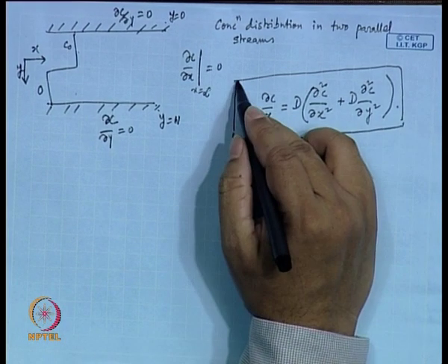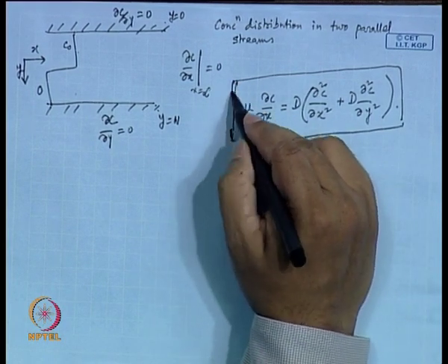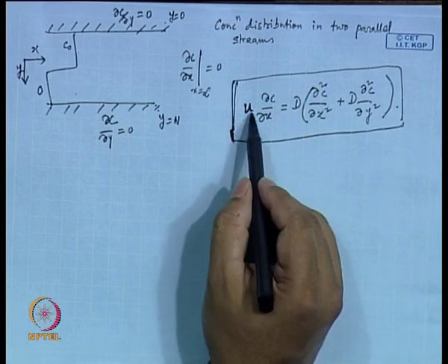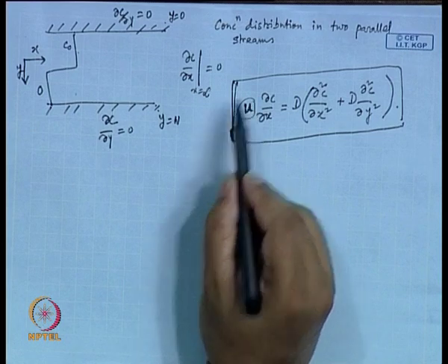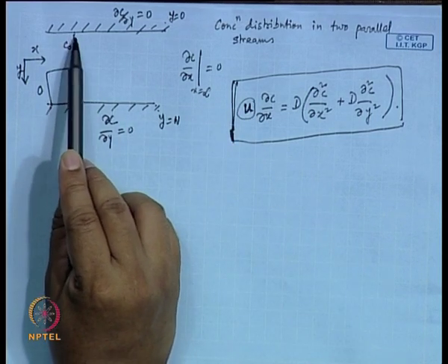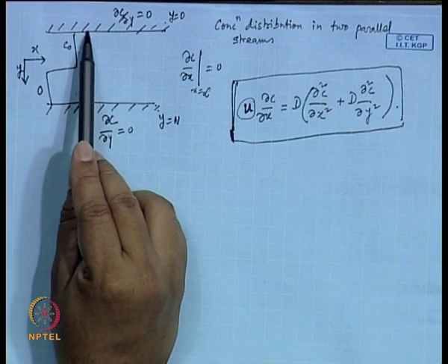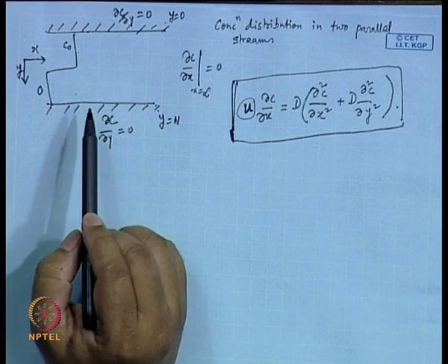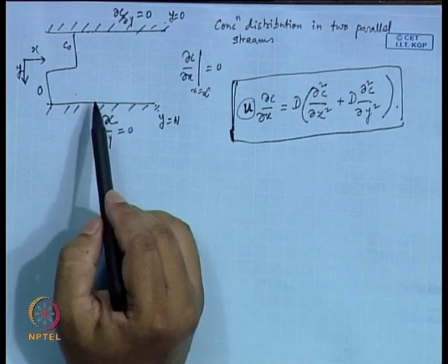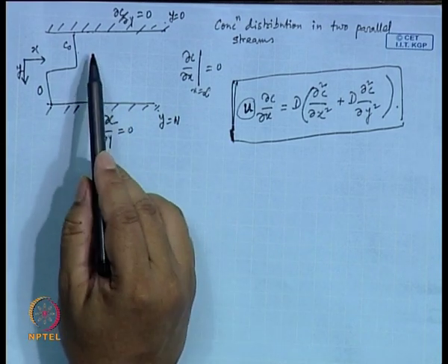So, these are the elements that you can consider at the least. Now, if you look at this u, what would be this u? If it is a laminar flow, you can expect the u to have a parabolic velocity distribution for a circular channel. So, u will be changing with y.